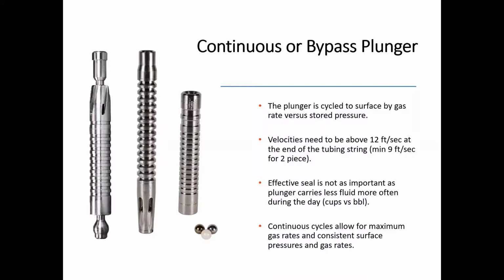Limited shut-in time for these wells also reduces stress on surface equipment, compression, because there are not large bursts of gas being sent during shut-in or after being shut in for an extended period of time. It is recommended to use a quality bumper spring when using these type of plungers because of the impact on the bumper spring and the fall speeds.